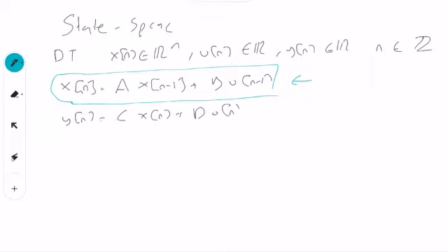You just start with initial conditions and simulate it. Technically it's a very simple for loop, forward in time, to compute x's and y's. In that respect, state space representation for discrete time systems is super useful, because understanding the behavior and finding solutions is much easier. In continuous time state space representation, in order to solve the system numerically, you need to use numerical differential equation solvers such as Euler or Runge-Kutta.